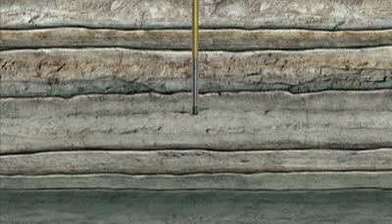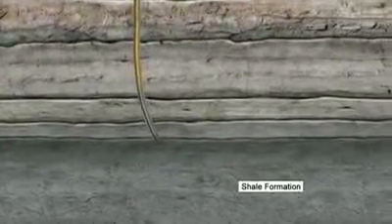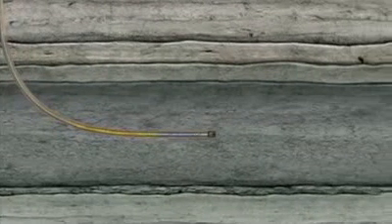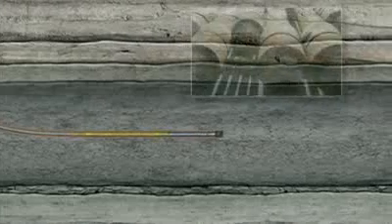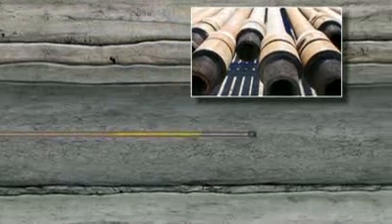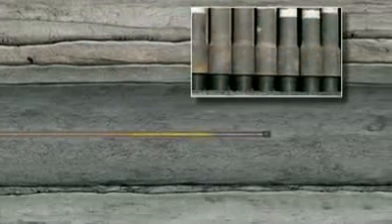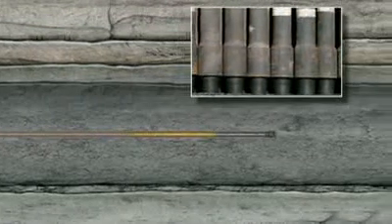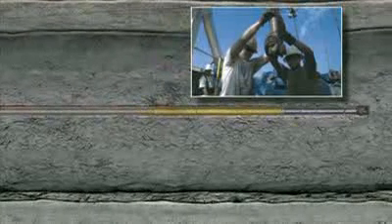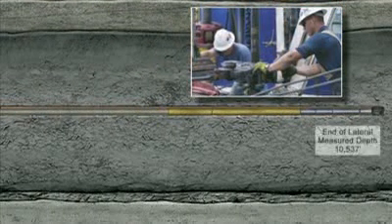If the plan is to drill a horizontal section, a special type of drilling device is used to begin to create the curved section. A downhole drilling motor containing a gyroscope is used, which can drill at an angle. Once the curved section is completed, drilling continues normally, but in a horizontal direction. A well might be 3,000 to 4,000 meters long, which will be lined with pipe placed permanently inside the hole. The pipe is made up of smaller sections that are connected together during the drilling process. Each section of pipe measures 10 meters in length.